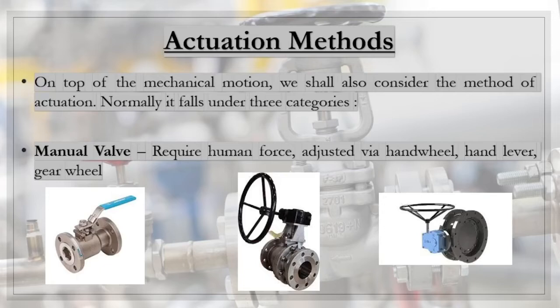If you can see my arrow here, I can't use the laser pointer. On the left hand side here, this is an example of a ball valve. So how can we operate this ball valve? You can see it here: this lever, which is wrapped in a blue color protector. So this is a quarter turn valve. How we use it is we turn it 90 degrees.